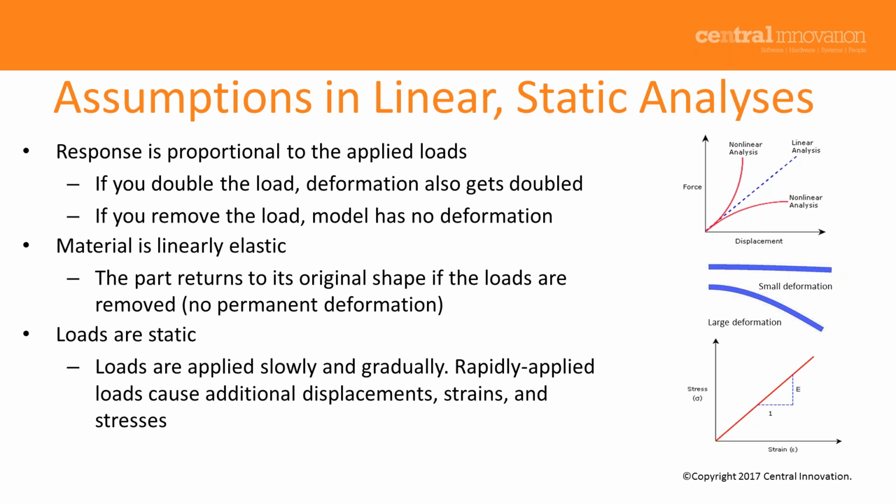Static means when the loads are applied slowly and gradually, and there is no time dependency. Imagine there is a chair, somebody is standing on it. This is a static load. Imagine if somebody is jumping on the same chair. This is not a static load because it's suddenly applied in a very short time frame. This is what we call dynamic.